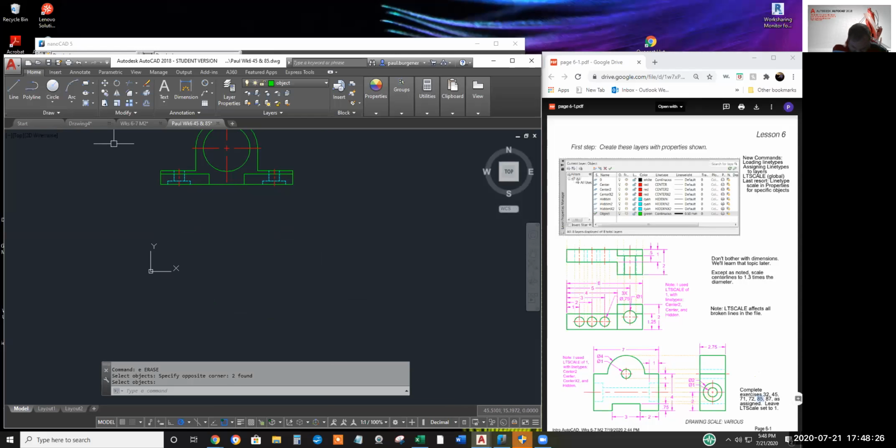All right, 85. Similar process. We'll start with everything is a diameter in 85. So we'll start in the midpoint. The biggest one is a diameter 37, enter. We'll move it down. We'll eventually get it back into positive. We'll click on center diameter again.